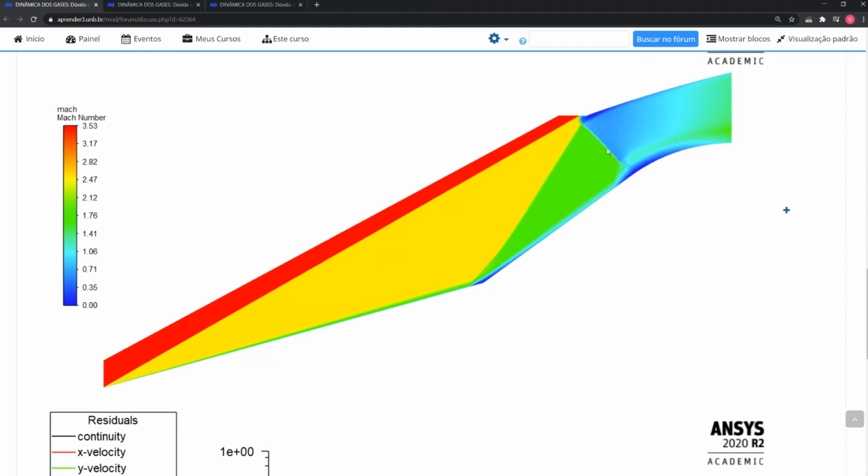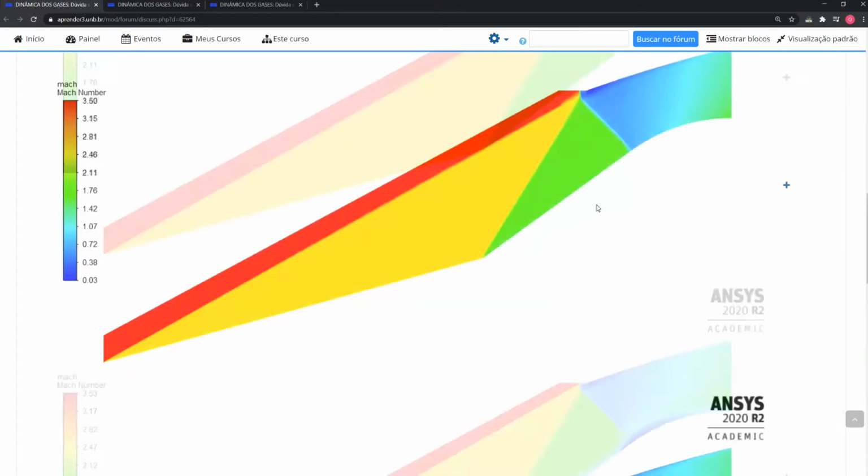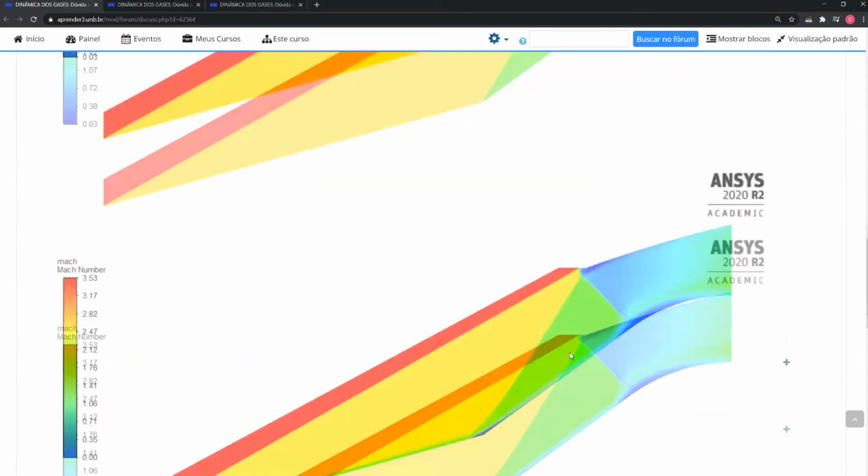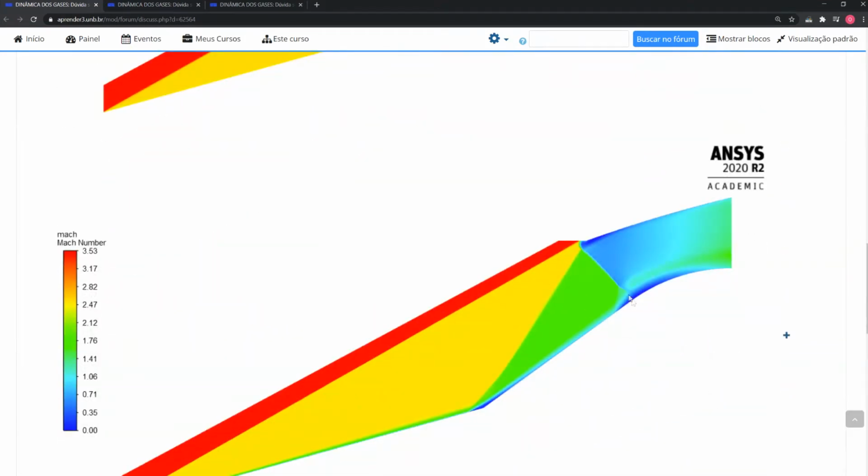And in this case, you may start to observe that the shockwave is starting to go outside of the diffuser. You do not need to wait until it's destroying all the flow. You just finish the simulation at this point when it has same configuration as this shockwave structure for inviscid flow, and you just stop the simulation.